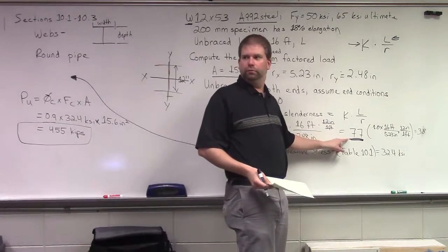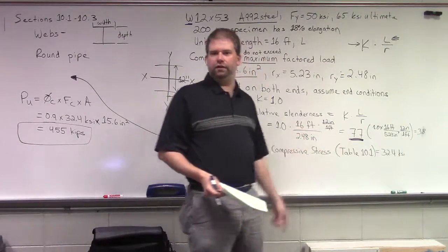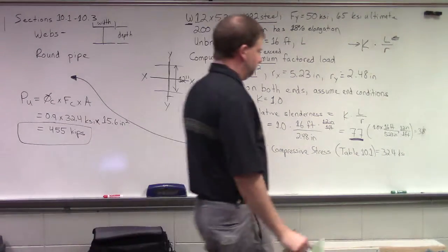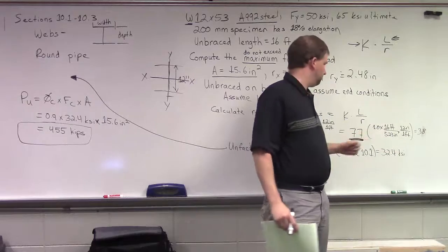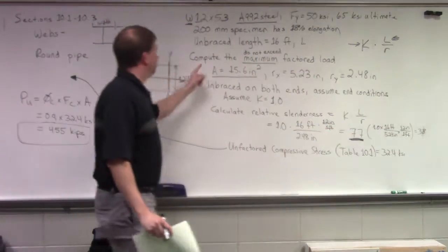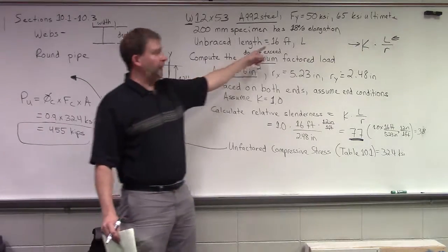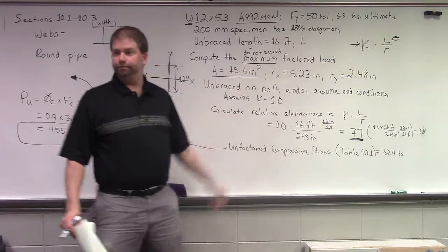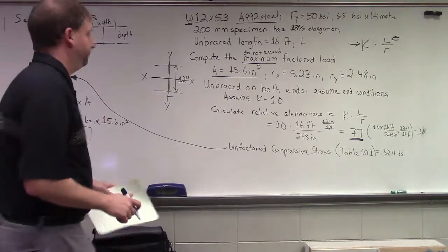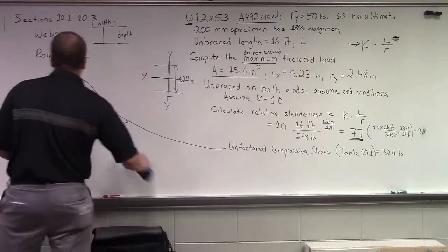So here we're at 77, so with that, we're happy. When you use 5.23, that would be literally too much bracing. What it's telling you is you don't have to hold back at 16 feet unbraced; we'd be overdoing it. All very good points.